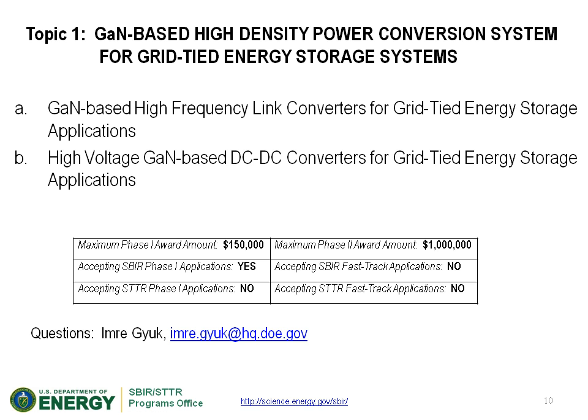To date, there are a number of silicon carbide-based systems developed, and more recently, gallium nitride has emerged with some promising characteristics. They have low on-state resistance and higher switching frequency, and they can both reduce conduction and switching losses.